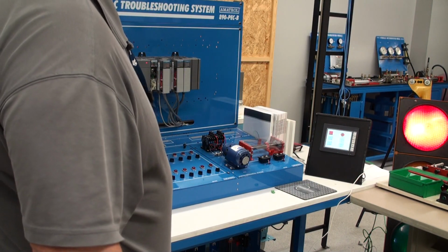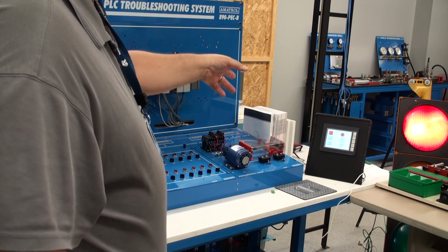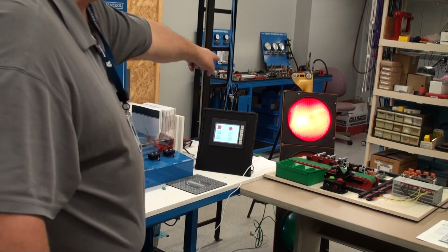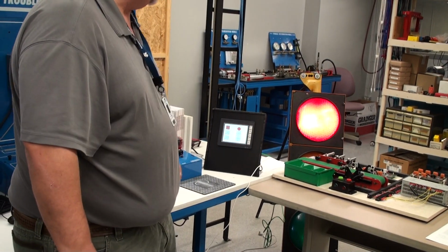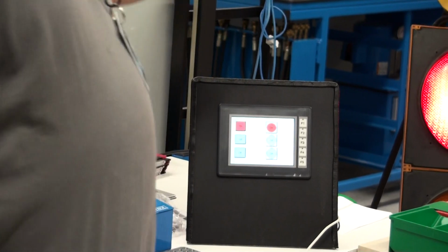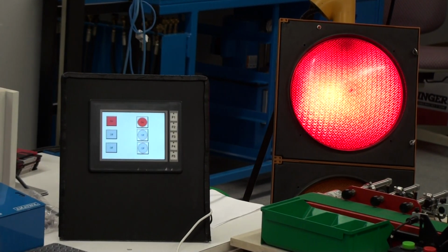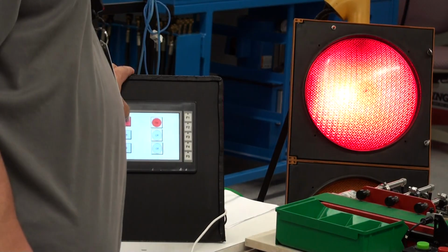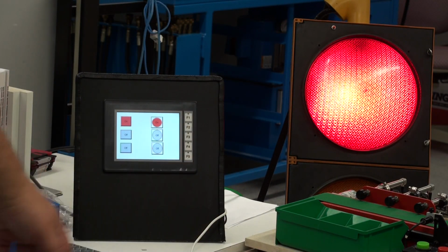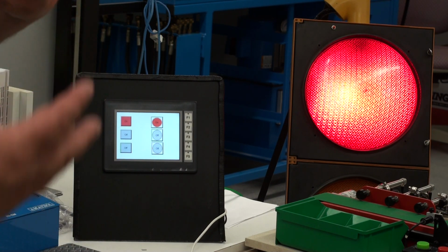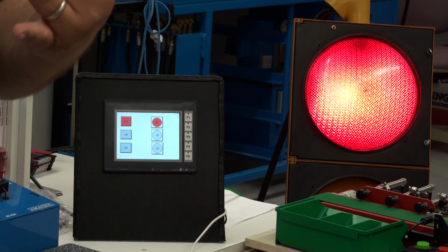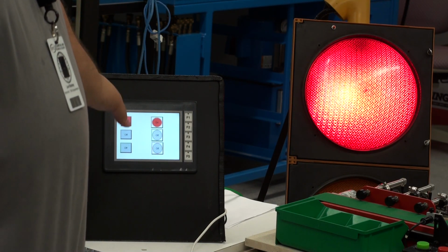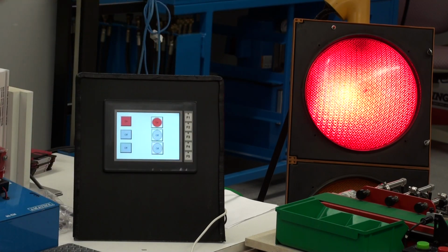But we've written a little program, and we're going to move over to the HMI, and this just gives you a minimal idea. We've got a traffic light over here that you can see, and we've got this HMI device, and you can't see anything but the red light. I understand that there's a lot to take in here, but we can actually control that output using this HMI, human machine interface device. We had to do that by writing a program for both the PLC and the HMI. But it's just one way that us humans can interact with a PLC and make things happen.